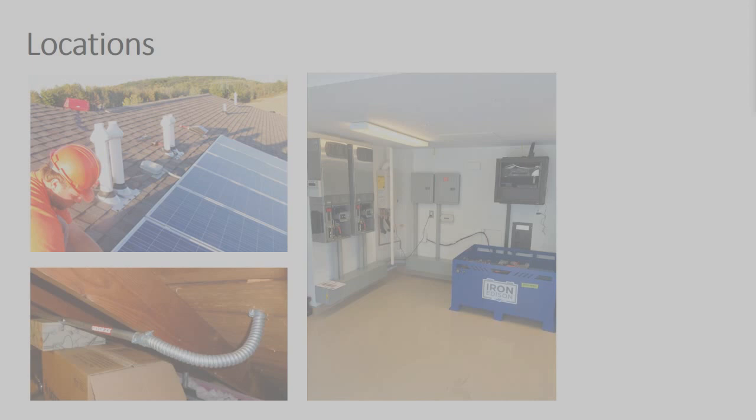So you don't need to worry so much about your material selection and what wire type you're using if you start with the premise of, okay, is my environment wet, damp, or dry? Is it going to experience high temperatures, or is it air conditioned and inside? Are there any batteries in the room, so I have to worry about a corrosive environment? Or am I right on the coastline, or am I on a chicken farm? What's a corrosive environment versus if there's no gas in the area?